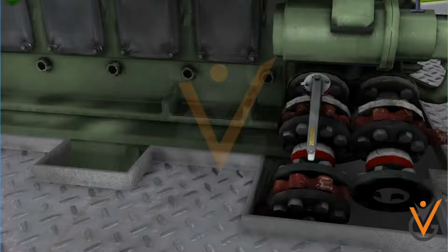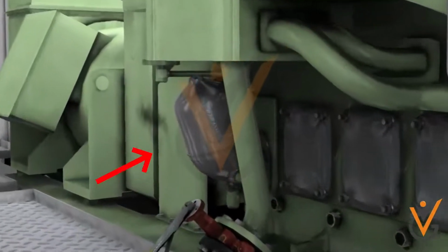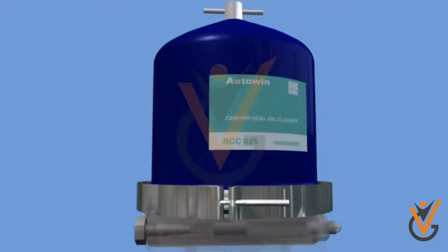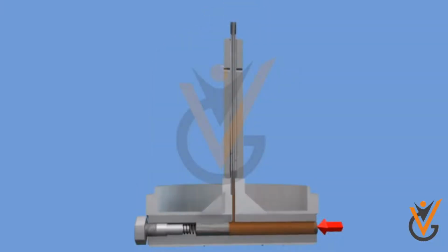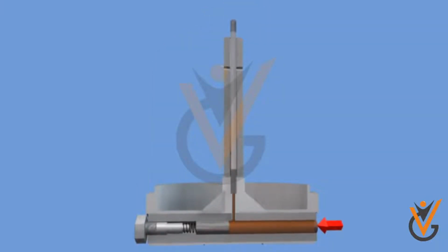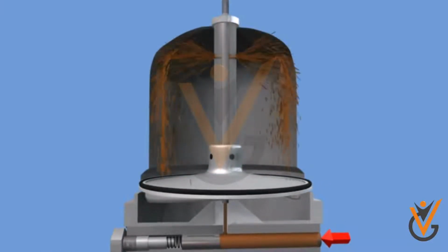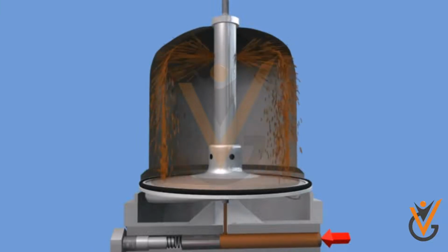Centrifugal filter works on the centrifugal principle. These filters work using centrifugal force to remove high-density fluids and impurities from the oil system. Lube oil enters from the bottom, pressurized oil comes out of the nozzle which creates centrifugal action. During the rotation of the bowl, dense sludge collects at the periphery. Clean oil drains to the sump.